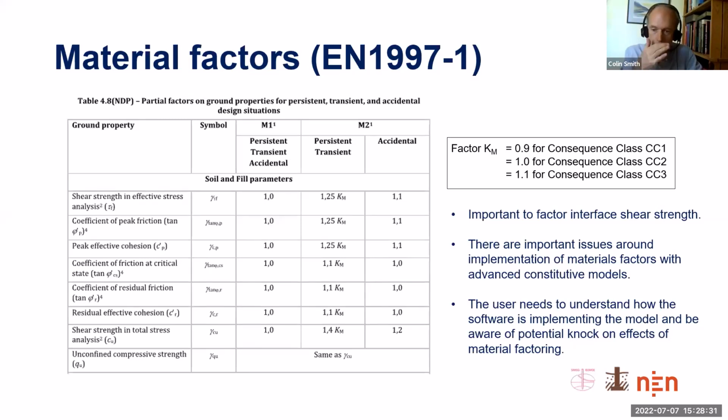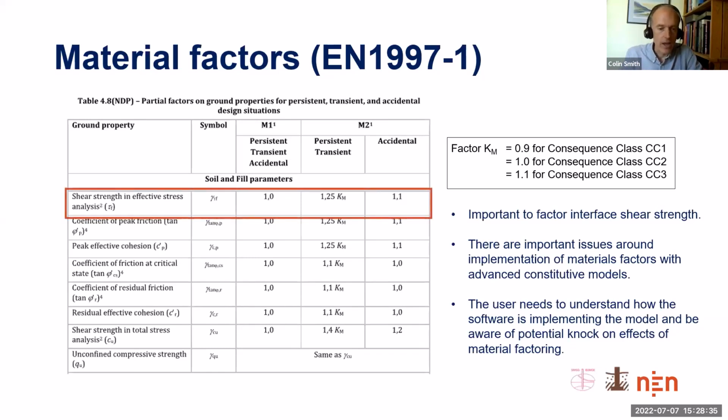So the only nod to that, however, is that this particular factor is directed at numerical models. So where you're doing an effective stress analysis that maybe feeds into an undrained assessment, then these are the factors that are recommended.